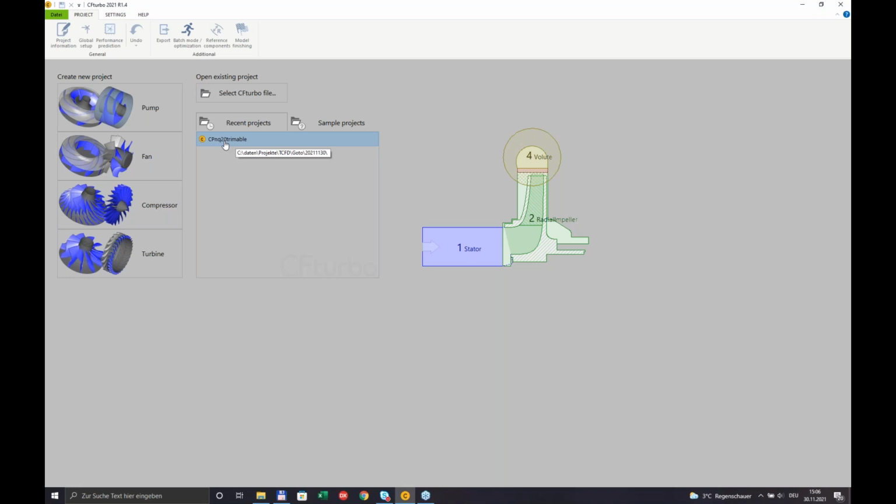It's a centrifugal pump, and a special geometric feature is that one can trim this pump and bring it down to smaller impeller diameters, and therefore is able to develop from one reference design of the impeller, for instance, a set of different designs for different operating points.